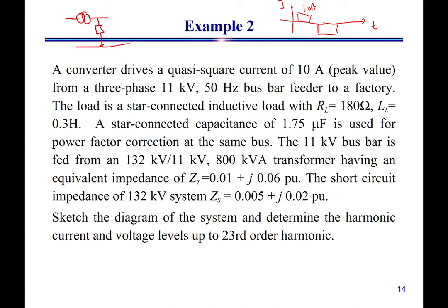The voltage over here will be 11 kilovolt. The load is a star-connected inductive load, so over here also we have a star-connected inductive load, R plus jωL, and we also have a capacitor bank. The value of C is 1.75 microfarad.